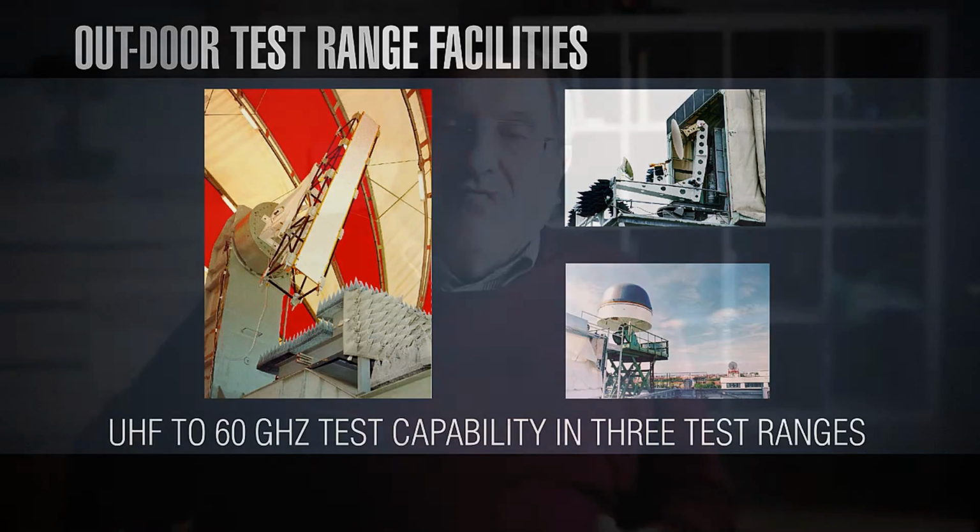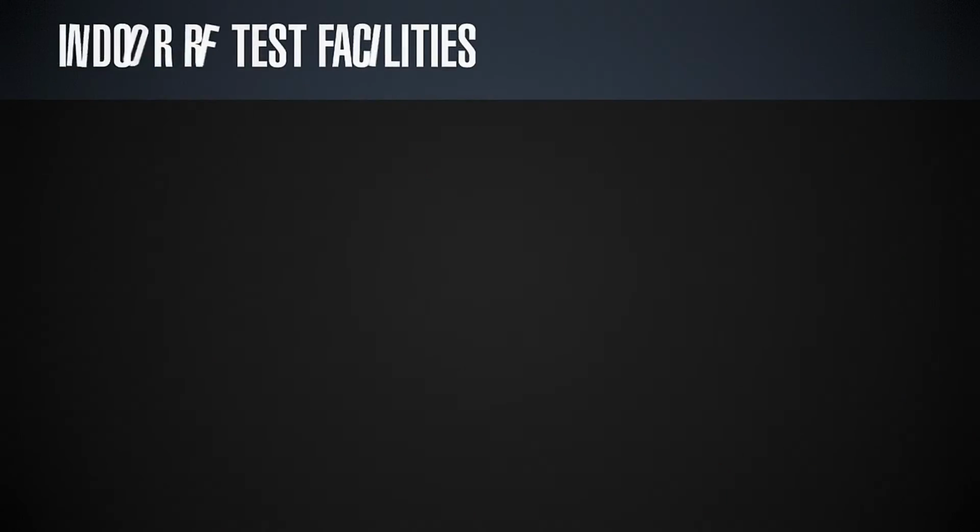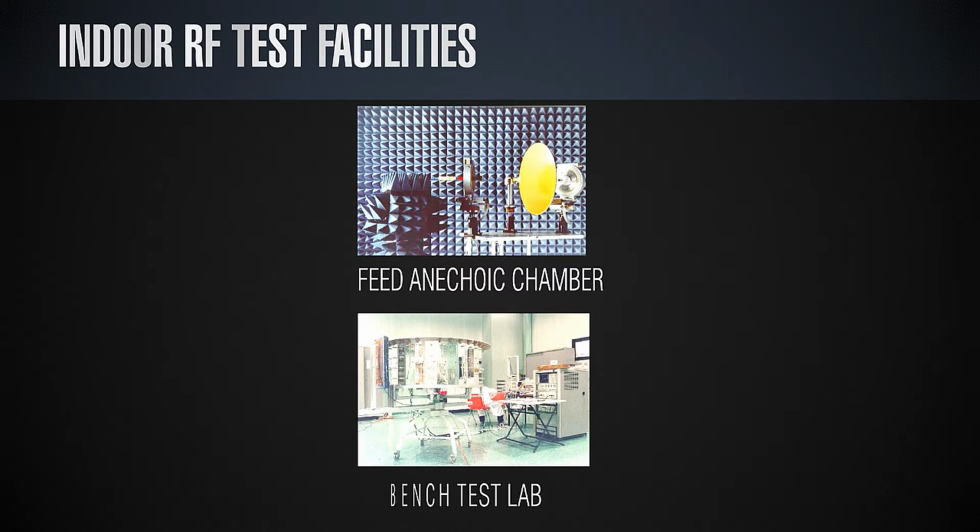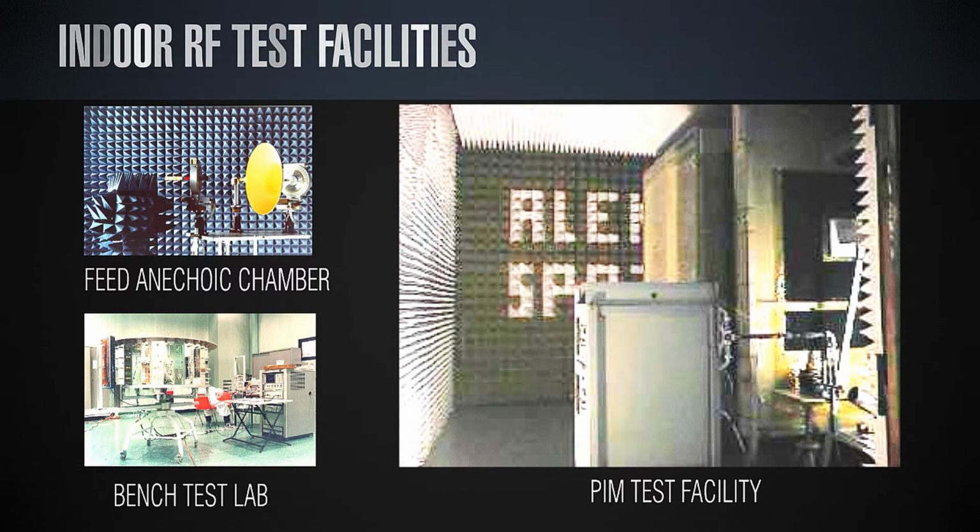There are other cases where you want to test antennas indoor because there you have a better control of the situation. This can be easily feasible, for instance, for small antennas, because we saw before that the smaller the antenna, the closer is the separation between the near field and far field. So for a small antenna or an antenna that works at very high frequencies, so although being small in physical terms is not small if compared to the frequency and the wavelength of operation, then you can still afford to